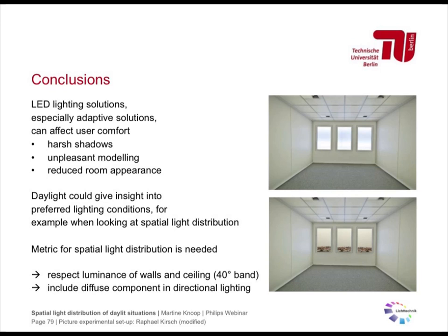Please be aware that the luminance of the walls and the ceiling play a role in the room appearance. Please keep in mind that they have to be higher than the ones that are proposed by the standards at the moment. And additionally, I would like to state that people or luminaire manufacturers that look into directional lighting include a diffuse component in these lighting solutions, either in the lighting solution in the room or directly in the luminaire.